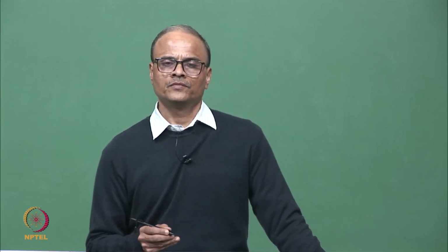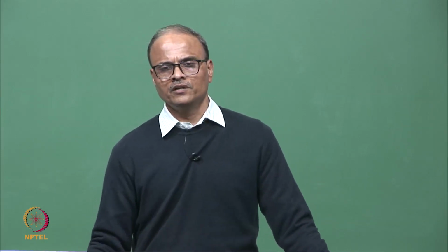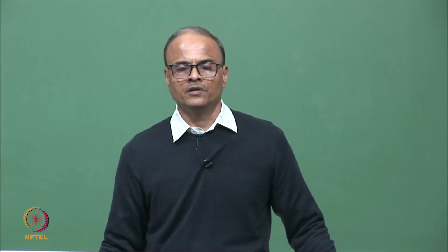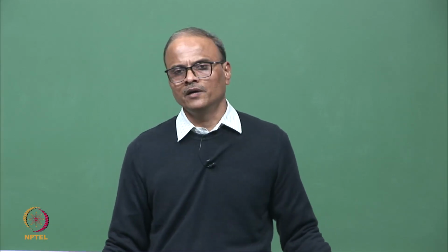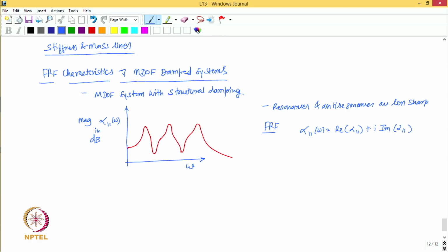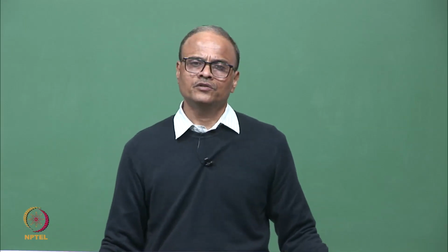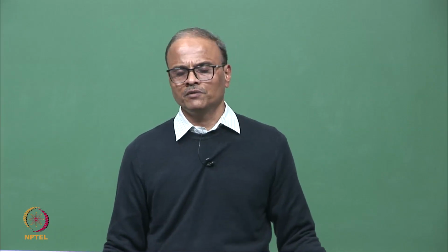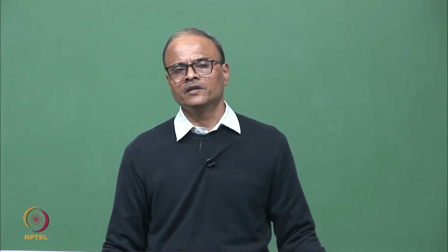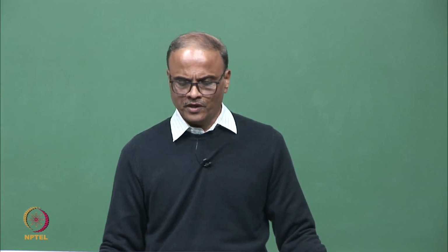and that is why for a damped system the anti-resonance frequencies do not have FRF magnitude 0. That is why the methods we studied for estimating the anti-resonance frequencies from the modal and the spatial model, the methods we studied for undamped systems, cannot be used in this case because the FRF magnitude is not 0. However, a rough estimate of these anti-resonance frequencies for damped systems can be found out by finding the anti-resonance frequencies of the corresponding undamped model.